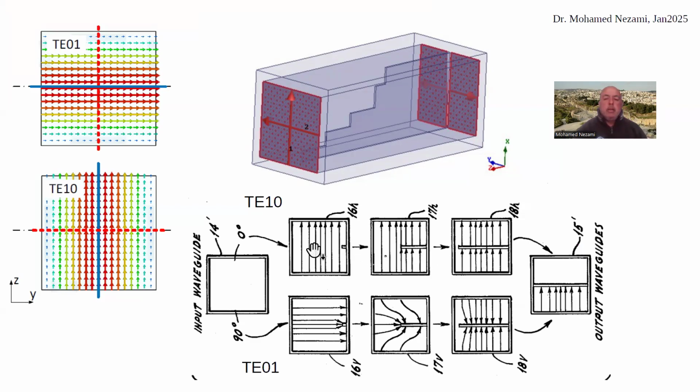The signal goes in here, and this line is the metal septum. It starts out small, like it is here, all the way until it divides the square aperture of the square waveguide completely into two separate compartments, representing two rectangular waveguides with half of the height. And that's really what's happening.